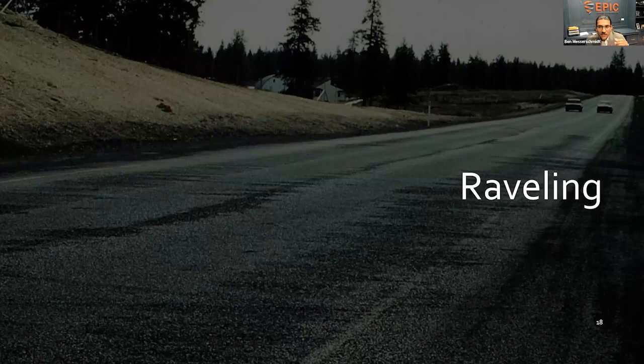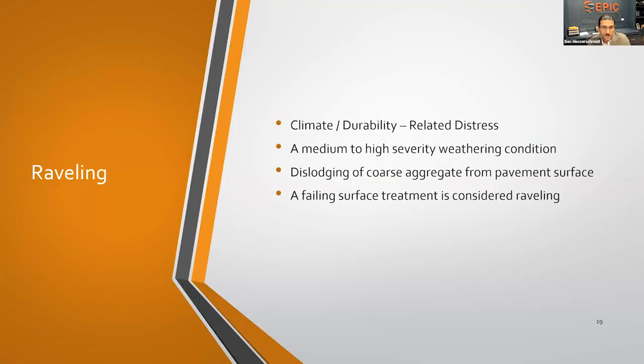But you're going to be dislodging the coarse aggregate from the substrate. So you're just creating more available pores and pockets where water and dirt and moisture can really sit on that system, as opposed to sheeting and moving off. And also a failing of a surface treatment is called raveling. So when your seal coat meets the end of its useful life, then the pavement surface will really be considered a raveled surface.